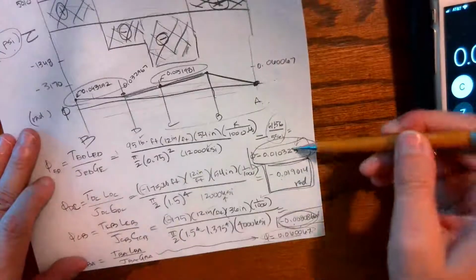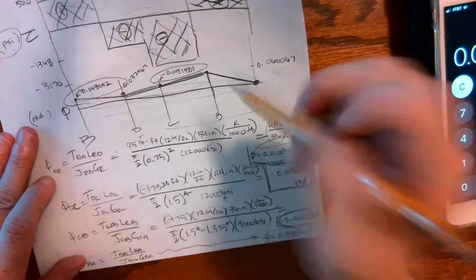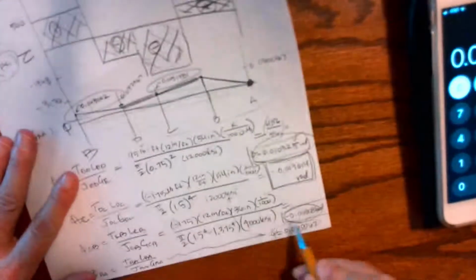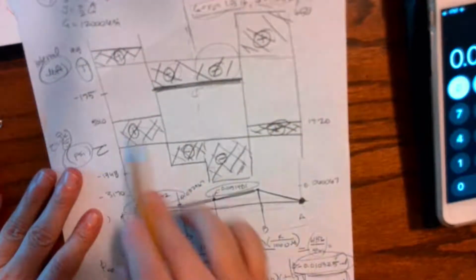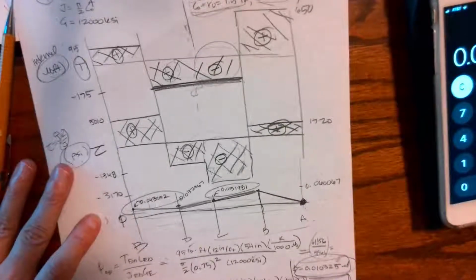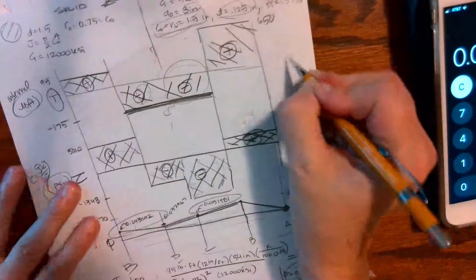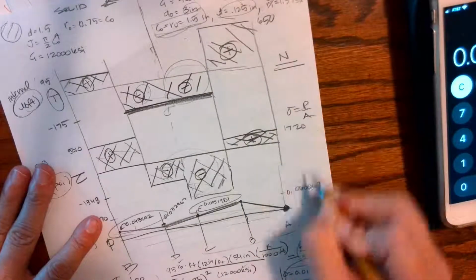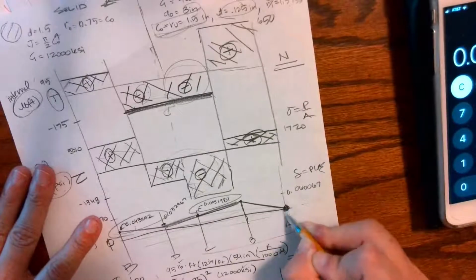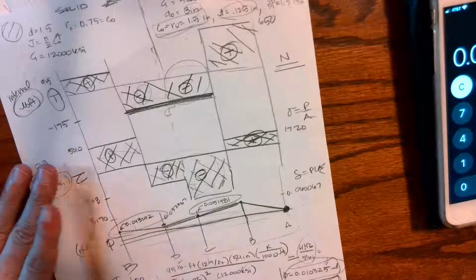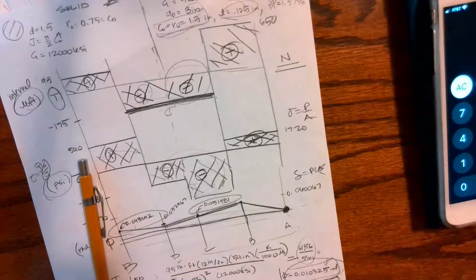So again, I calculate it for each segment. Everything was with respect to A, so there's my starting point. And then I just either add or subtract depending on if it's positive or negative. And that came from whether my torque was positive or negative, and likewise my shear stress is positive or negative. And just sum it up, it's a lot like the delta. This could have been internal normal force, this could have been internal stress, P over A, and this could have been my delta. And at the wall, I wouldn't have any displacement, but as I went down the length of that shaft, I would have displacement. So it's the same thing, just a different application because it's a different stress.